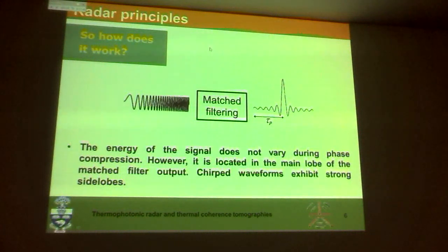On the other hand, thermal conductivity is a static parameter. That is, usually I have a wall here, I have a window, there is a temperature T1 here, a temperature T2 there, and then there is a temperature gradient. So your windows have to have low thermal conductivity, right? If your windows are made out of copper, you're in bad shape, because the cold weather out there is going to be transmitting itself immediately. The temperature is going to be low inside your apartment, which you don't want. You want to use glass, because glass has a very low thermal conductivity, so the temperature gradient between the front and the back is going to be really large. Very low temperatures here, high temperatures there, because you're heating the apartment.